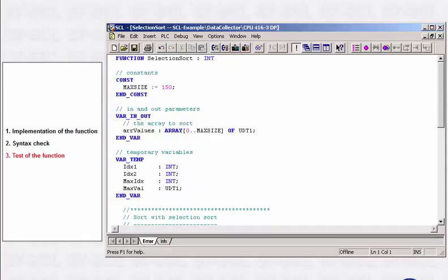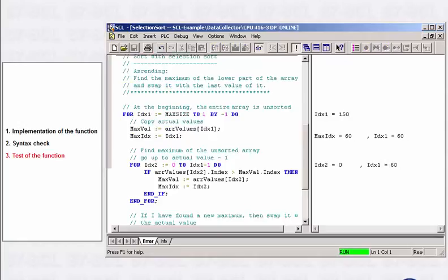The functionality should now be checked online, because often errors are only discovered during runtime. First, the S7 SCL block is loaded into the automation system. S7 SCL gives you two options for checking the functionality: program status and single step mode to monitor variable assignment step by step. To monitor the program status, you simply click on the spectacles icon. In this way, variable assignments that occur during the block run can be observed online on the CPU. This is useful above all in finite state machines where statuses last for several cycles. With this function, however, you can't see very much, because the changes happen so quickly.